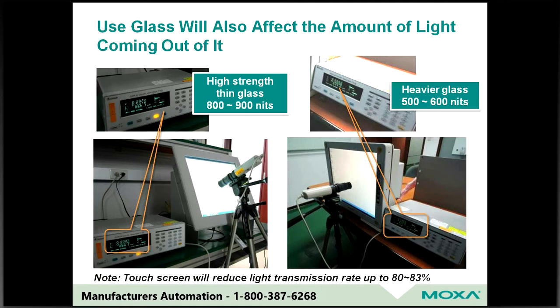So generally, we recommend over 7,000 nits for any panel PC that has a strong requirement of visibility for the operator to control operations. You're going to want that, because when it's all said and done, you're going to lose about 1,000 to 1,200 nits just by having a robust screen and insulation layer under that screen for your panel